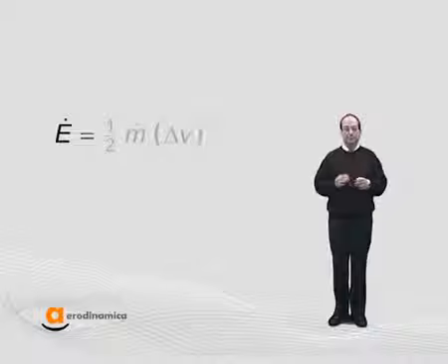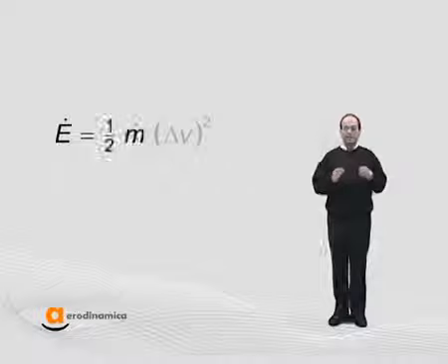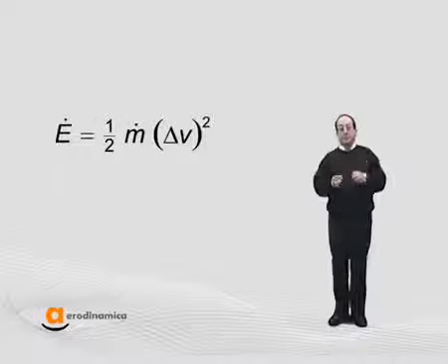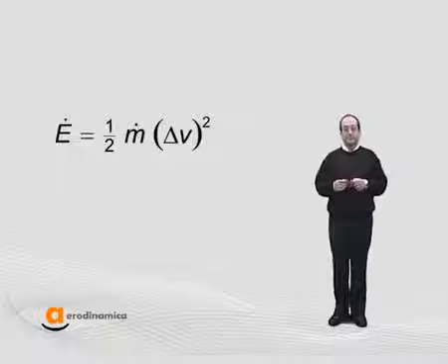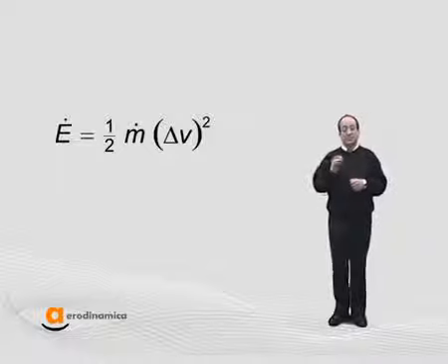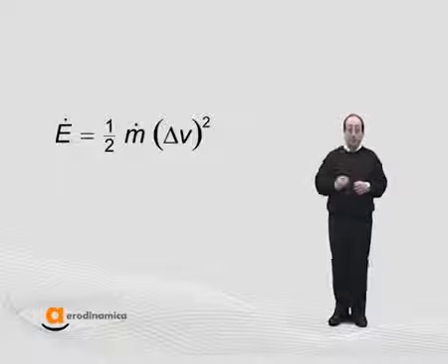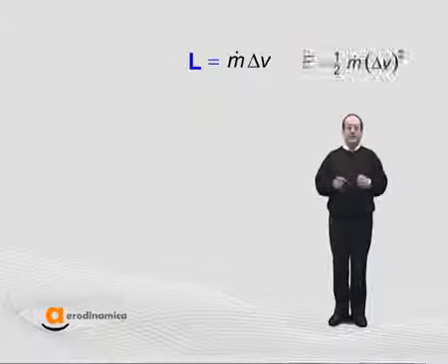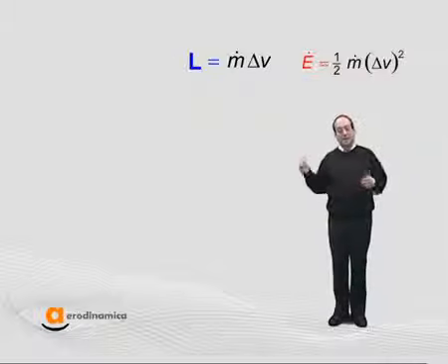The wing transfers kinetic energy to the air through its movement. The variation of the kinetic energy in the time unit given to the air gives us the power we need to gain the lift force, as we can see from this formula. If we have two wings with the same surface but different wingspans, the power necessary to gain the lift force is less for the wing with larger span. Wings with a larger span can move a higher mass of air.